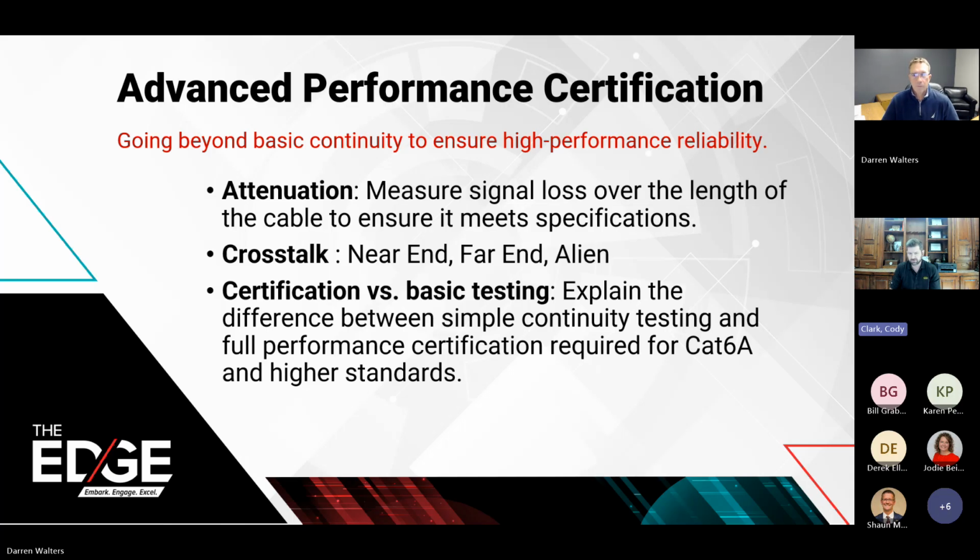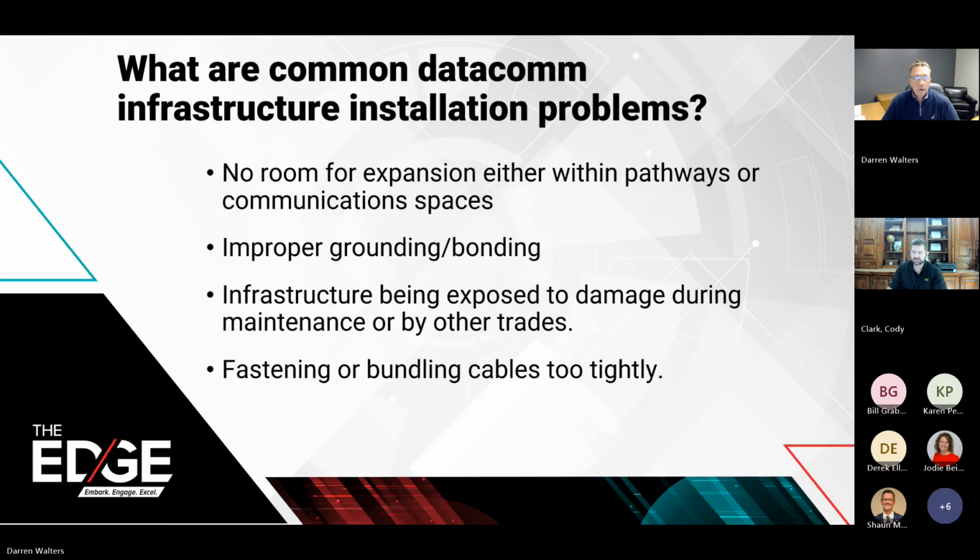Or on alien crosstalk, are you having other cables around your bundle of cables or your pathway that are causing interference onto that cable that's going to cause you issues with your data transmission? So it's just taking it to another level. And for any new installation, anything that you're not troubleshooting, I'd highly recommend doing a certification test over a basic 4-pair test, especially at those higher performance Cat 6, Cat 6A solutions.